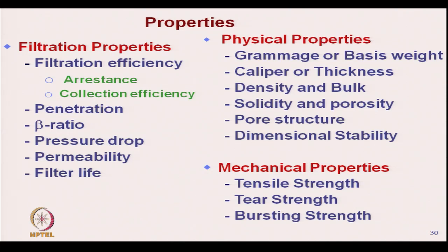basis weight or grammage, thickness, or sometimes it is called caliper, density and bulk of filter fabric, solidity, that is amount of solid content or porosity, pore structure, and dimensional stability.